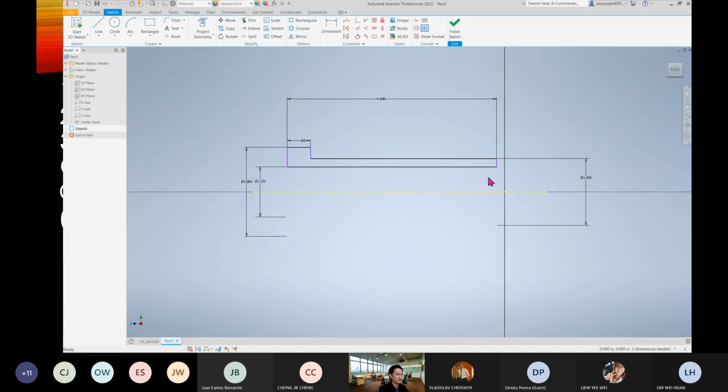So it's not fully constrained yet because they're still moving horizontally. But now you can see that I'm having everything here. Okay, if you want to have it fully constrained, you don't need to move. You can drag this and then snap on the axis. If you want to snap on the Y axis, I can once more borrow the Y axis, create a line. So I just snap it on it. So now I can see that my whole sketch is fully constrained.